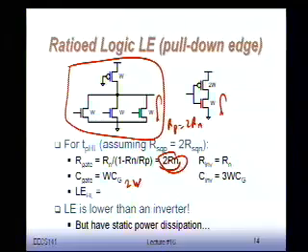So it's 2 times W. For the inverter, we have 3 times W. It becomes, once again, 2/3, which is exactly the same as we had for the low to high transition. So in both cases, our logical effort is 2/3, which shows that this gate, definitely from a performance perspective, is a good choice.